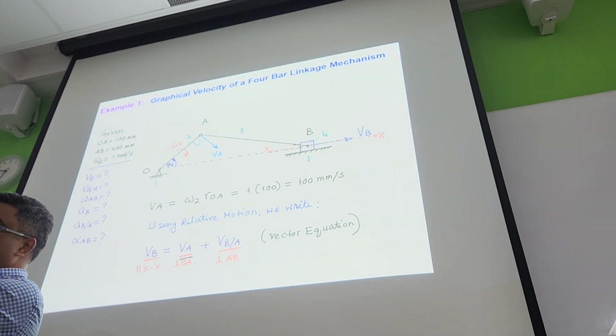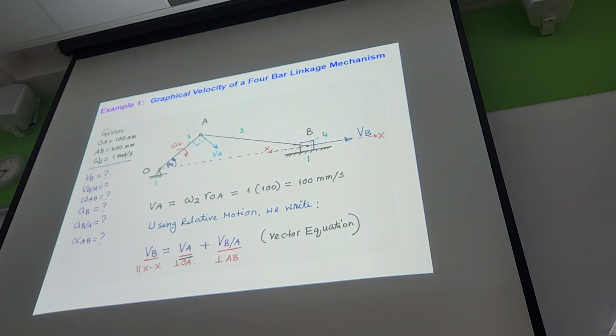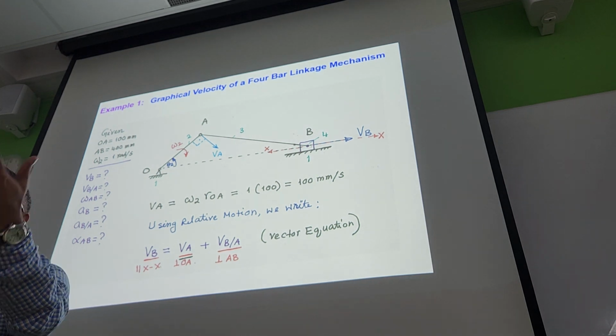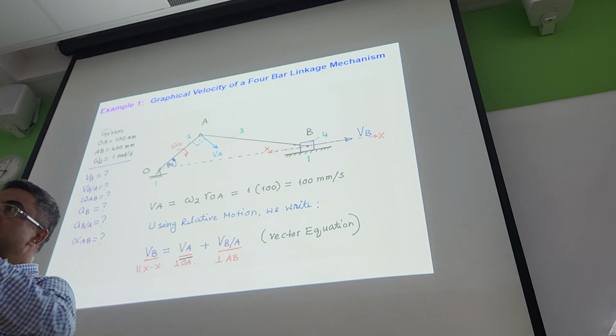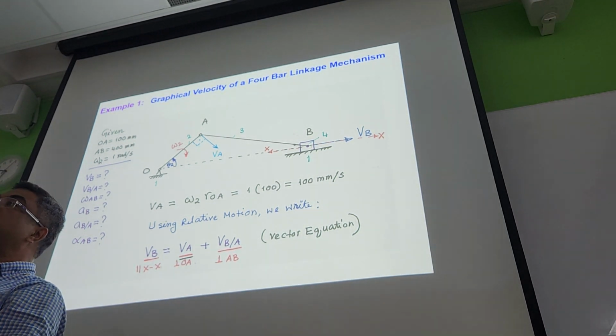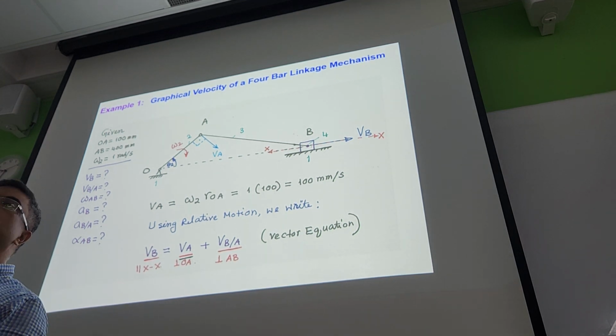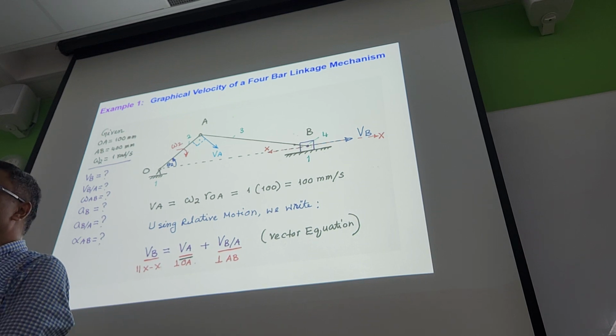So this connection, this one and this one, you cannot connect. That joint should not be rectangular or very sharp because there is a lot of stress there. It needs to be a very nice curve, and you cannot do that in a normal calculation, how the stress will be distributed so that it will not be concentrated in the joint. So we use the graphical method to get this connection, and then we replicate it in our manufacturing system.